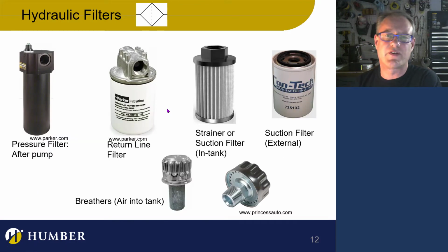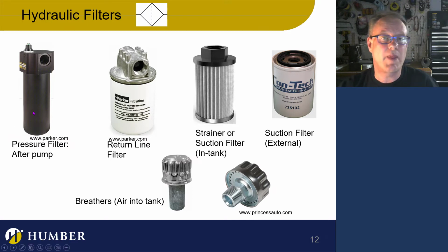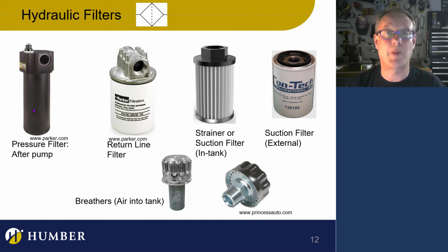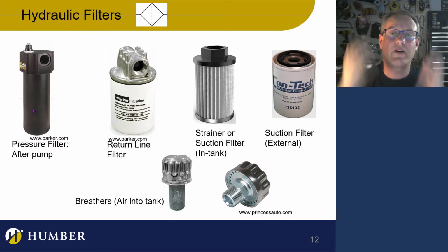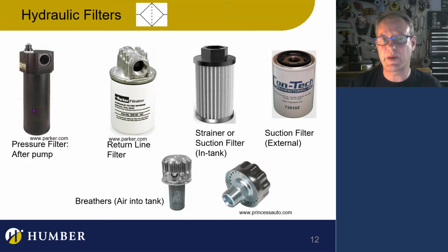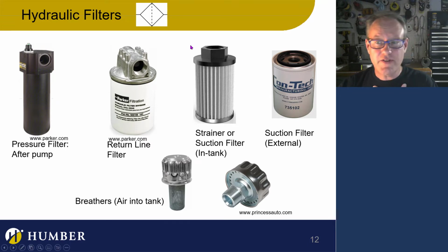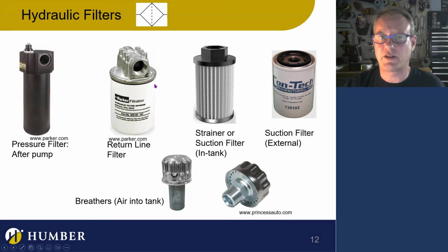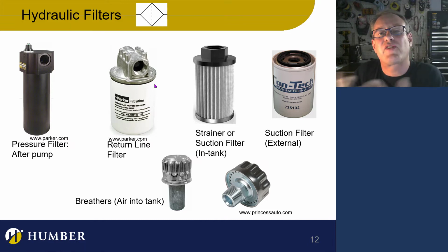Let's take a look at a few different system filters, and then I have a picture where we can see the whole thing, and we can see where all the filters go. There are these inline filters, and they're actually on the pressure line themselves. They will clean out the smallest particles, the very, very tiniest particles. And the reason is because they're under pressure. So essentially, you can have those with the finest filter. These other things can't handle really, really fine filters because it's hard for the fluid to get through them.